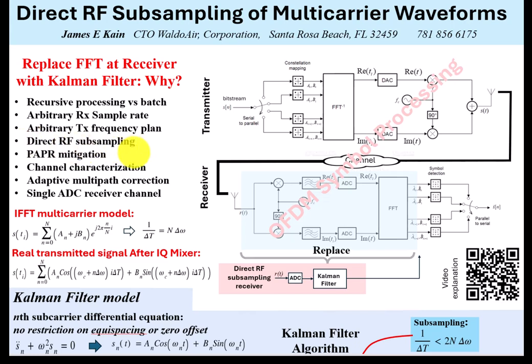But implementation of direct RF methods are hindered by the digital processing requirement at these extreme speeds. That's where subsampling at well below the carrier will enable practical commercial implementations of direct RF radio. This uses the bandwidth of the fast ADCs, but the slower sampling reduces the processing demands.